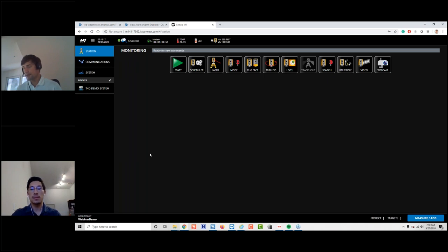And there was another question from Martin, if we also support a least square adjustment. At least this is how I understand the question. So the answer is yes, T4D supports a least square adjustment. So you can imagine if you combine multiple total stations in one processing engine, so to say, we can adjust all the measurements of every total station together in one flow. So this is fully supported.